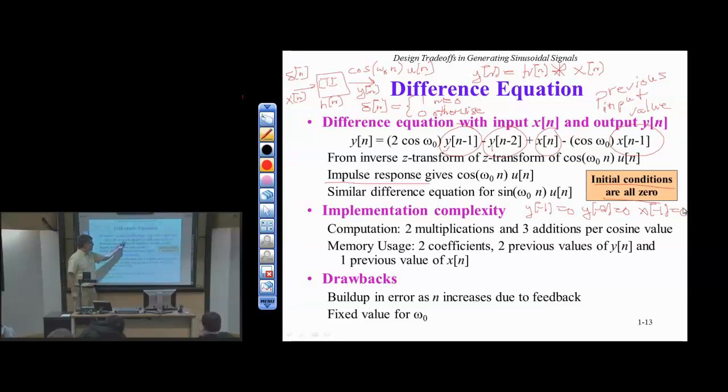Every time I multiply 2 numbers together, I get more bits than I started with. So if this were, let's say, 32-bit float and 32-bit float, the worst case result, so 32-bit float has 24 bits of mantissa plus sign, 8 bits of exponent. If I multiply these together, I need 48 bits of mantissa, double the number of bits of mantissa. But in implementation, I'll truncate this back to 32-bit float. So I take the 48 bits of mantissa, truncate it back to 24.